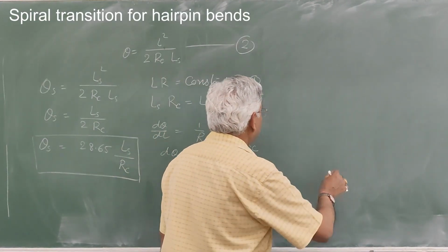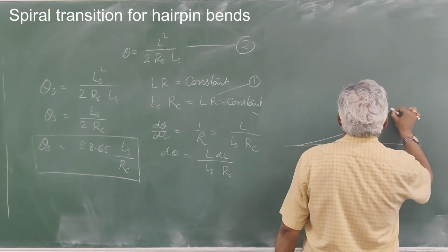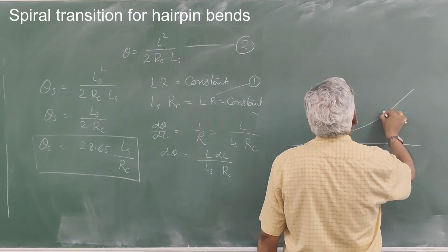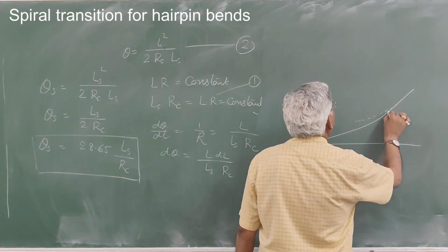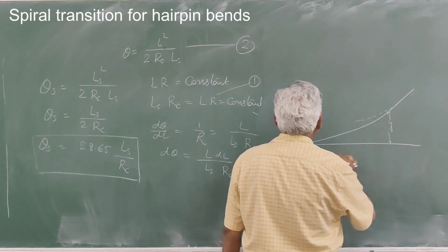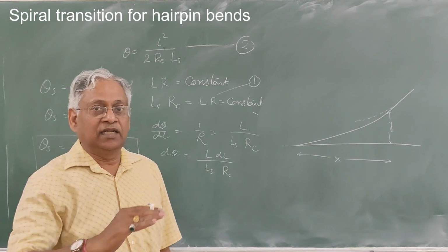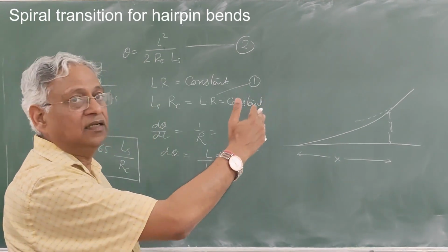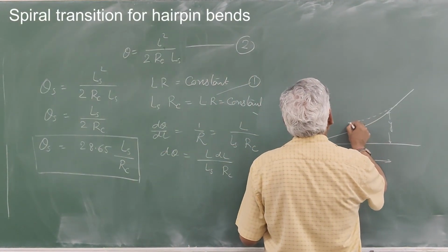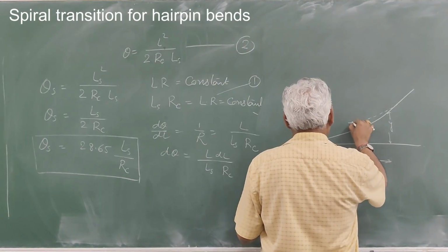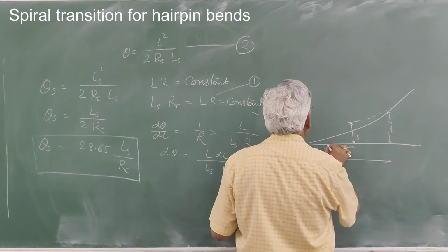For the purpose of setting out this curve, this is the transition and you have a circular curve here. The offset y is taken at, let us say, distance x. X is along the tangent, whereas L is along the transition. And this is the shift S, which is taken at a distance k from the tangent point.